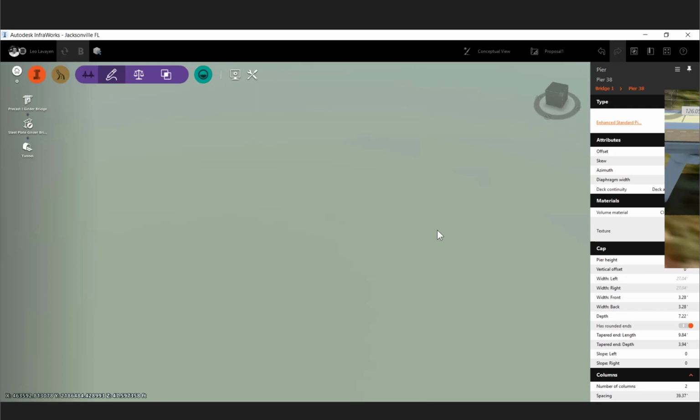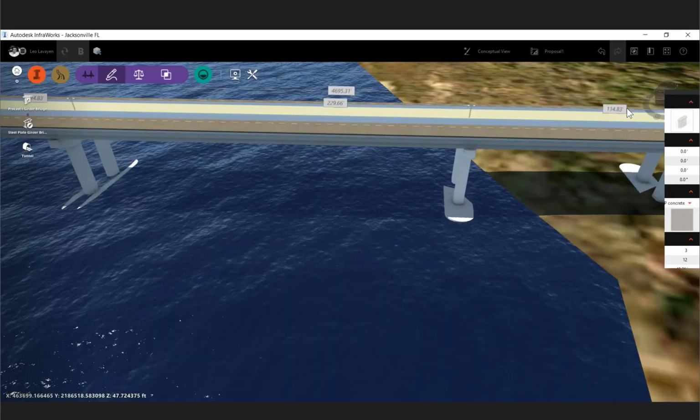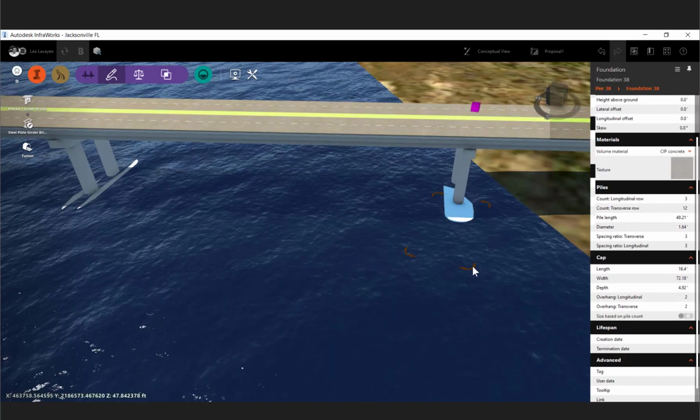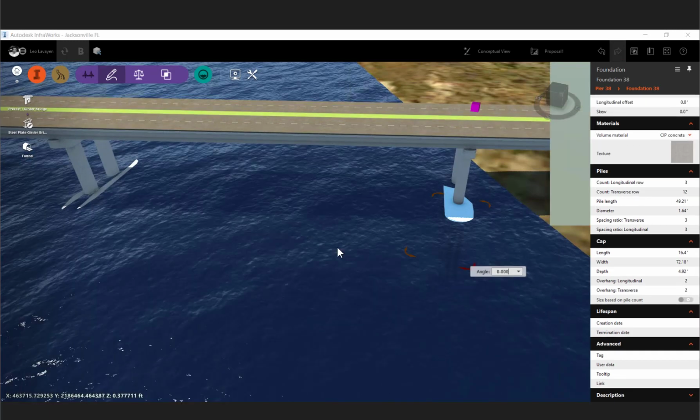And I can see what options I have here from what looks like it's called an asset card. It looks like the AutoCAD properties tool palette, and I have options of how to play with all the values that come out of the box here for myself. Or in this particular case, just simply on screen, use the grip edits to rotate it and have that particular pier be more in line with any existing features or proposed features on screen here.